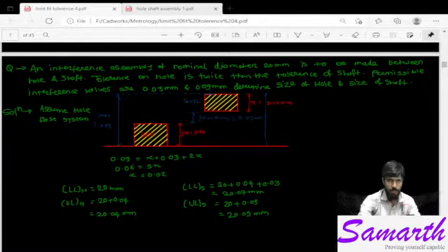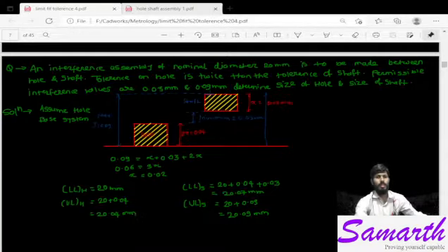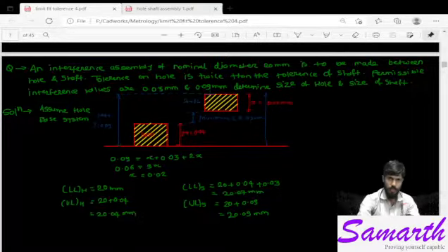This much complete distance we get by adding this 20, the basic line, plus this tolerance, plus this interference. Again, by adding this much distance, that is tolerance on shaft, we get the upper limit for the shaft. Here we have calculated the upper limit. That is the complete maximum interference we add to the baseline.